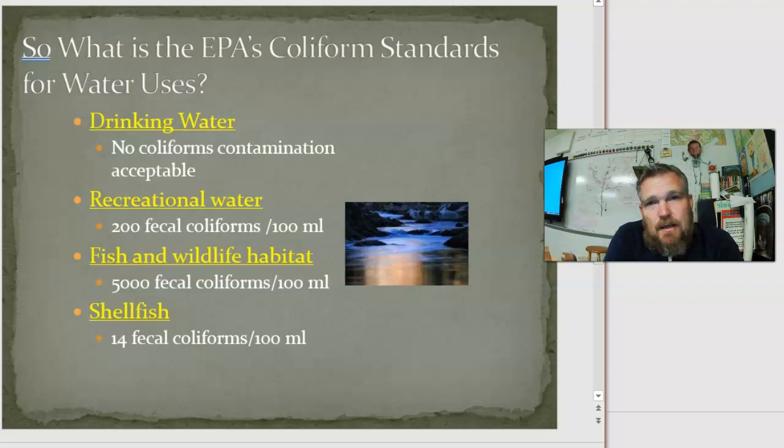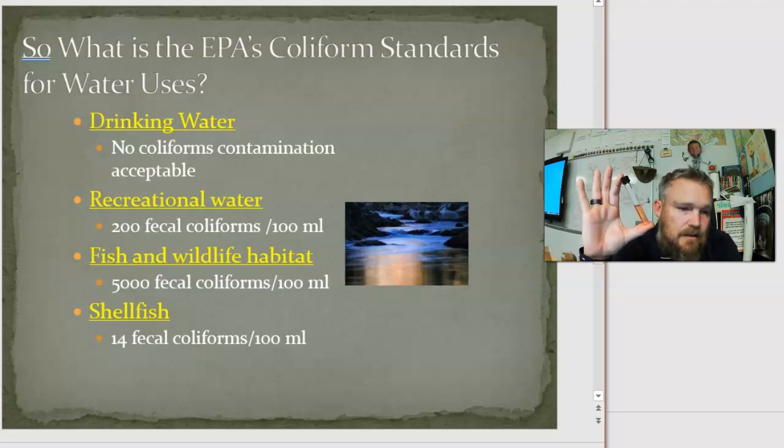So the reason, like, we got a boil notice on Thursday, and then they said, we will let you know on Saturday if you can return to drinking the water. And the reason for that is because they use these. Okay, this is a coliform count test. And if you were here right now, we're actually doing this in class. But this guy is kind of an orangey red color. And that is indicative that there are no coliforms in here.